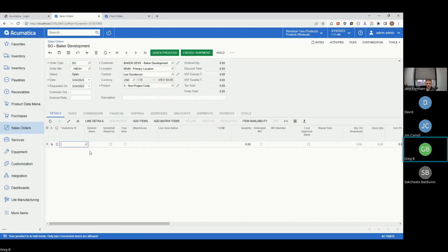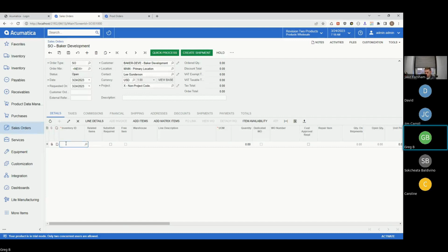And we'll go in, and now what we can do is create some kits to repair an item. And let me give you an example of where that might be. Say, for instance, you're in the business of selling hydraulic cylinders. Everybody knows a hydraulic cylinder. It's a simple machine. It's got a rod, and it's got a barrel, and it's got a piston in there, and then there's seals in there that seal the rod to the flange nut in the end of the barrel, and seal the piston to the inside of the barrel, so that when it fills with hydraulic fluid, it extends.